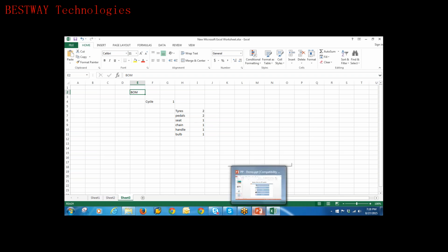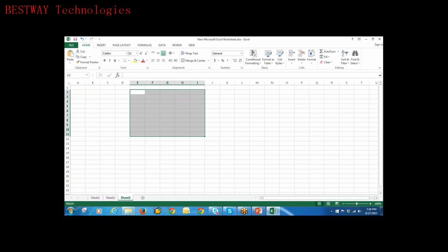Once the BOM is done, we will move on to another one. For the time being, I will go ahead with another example. Let's take curd. To manufacture curd, what do you require? You need milk. Okay, good. And after that, you require some sample curd, which we will call yeast. So if you are trying to produce curd, your curd is your product, the one you are going to manufacture. For that you require milk and yeast. So those will become the components in the BOM.